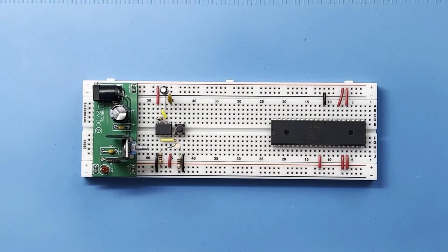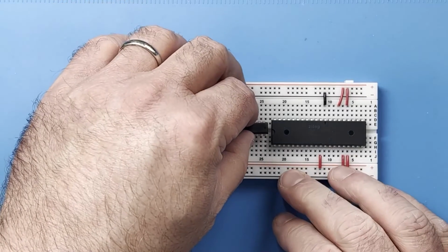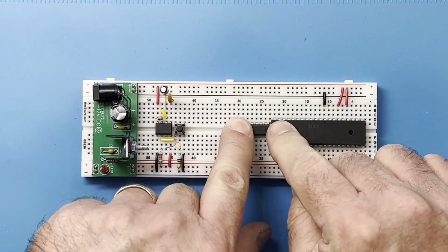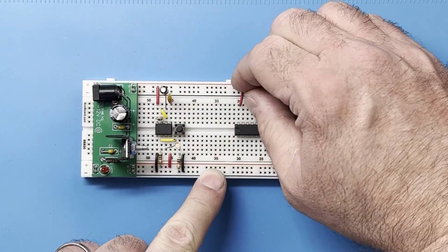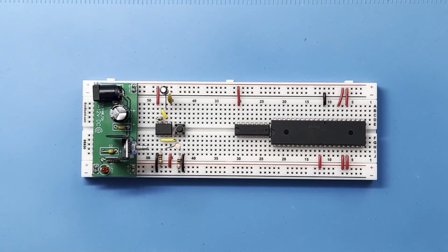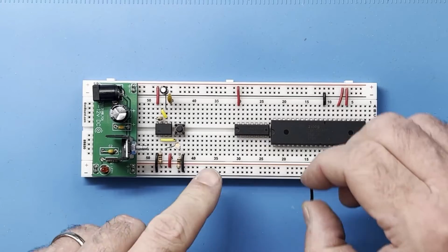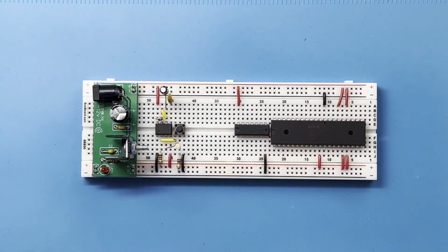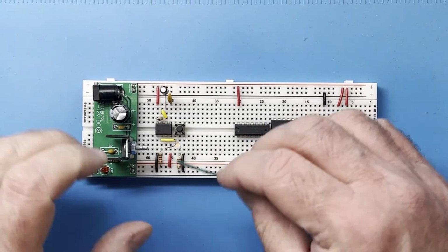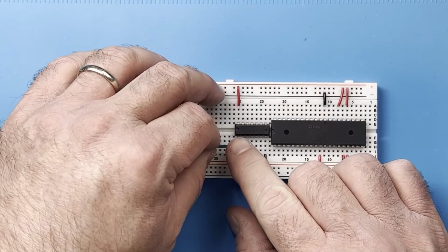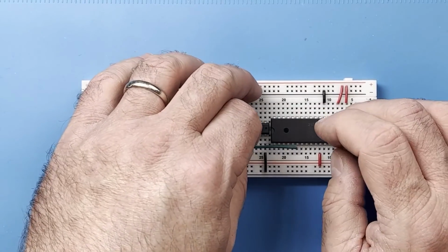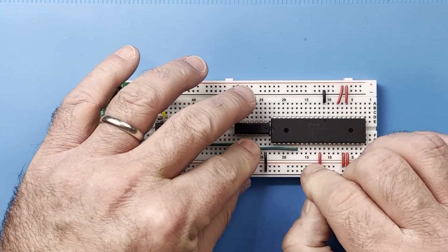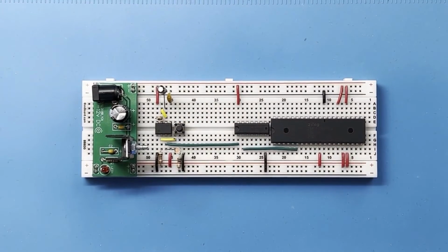Okay, so let's go ahead and hook up the clock. But if you remember from our pin discussion, the clock is active low and our push button is active high. So we need to invert the clock signal. I'll use a 74 HCT14 Schmitt trigger inverter for that purpose. So let's get hooked up with power and ground, power on pin 14 right there, and ground on pin 7 right there. And then I'll run our clock from pin 3 of the 555 into pin 1 of the HCT14. And then I'll run the output of that on pin 2 to the clock on the Z80, which is pin 6 right there.